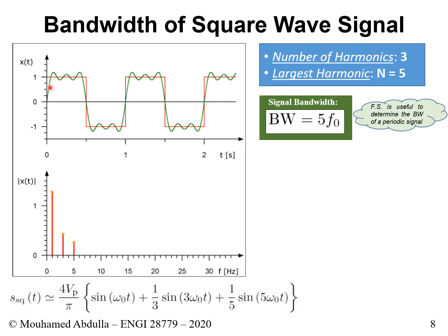If you look at the estimate, it's already shaping up to look much nicer. The estimation is becoming quite good and looks closer to the square signal. Remember when we only had this one here? It was very bad, just a sinusoid. It did overlap, but not quite. Now with 3 harmonics, it's shaping up quite well and looks much better. You can also notice these 3 peaks, 1, 2, 3, which means that you have 3 harmonics. That's another way of looking at it.